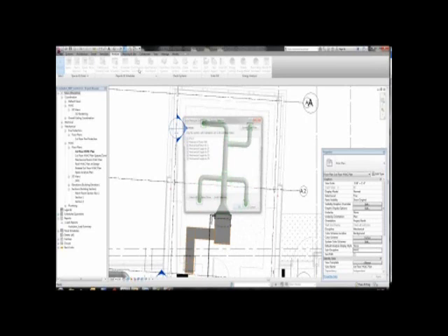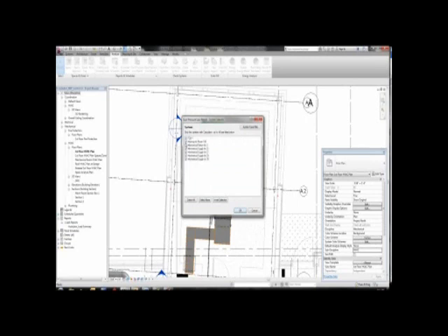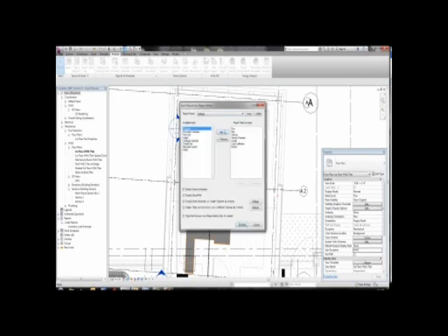And I'll go to the system type filter, because I could do the exhaust air, return air, and supply air at the same time, but I'm just going to do the supply air right now. So I have that set. Click OK. And then I can just choose whichever fields I want to add to the actual report. So you can see we get some default information in here. And I can also click some of the other parameters there to display system information or critical path. But I'm just going to create the report. I'm going to save this report. I can save it as an HTML file.